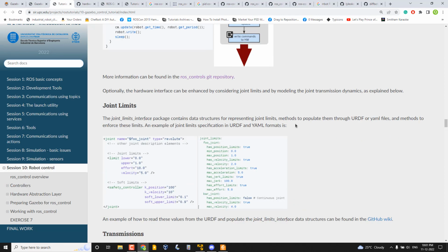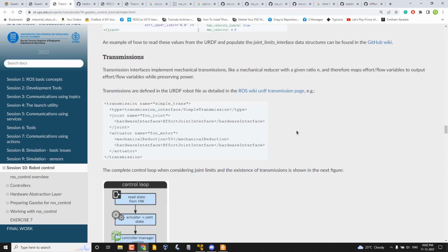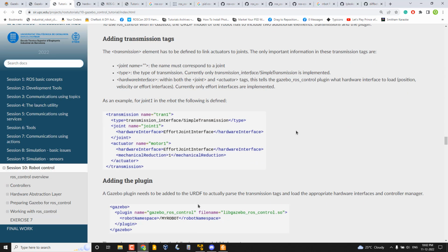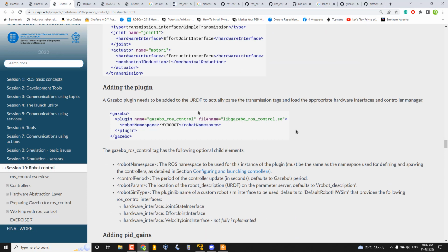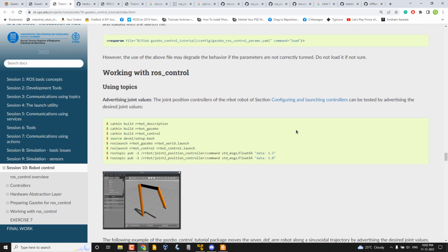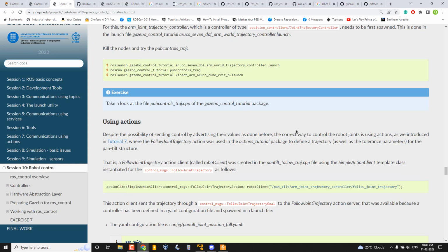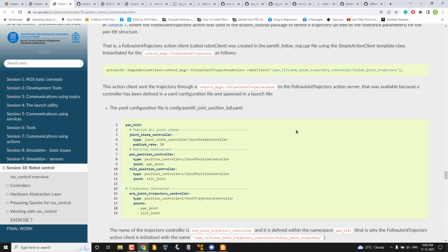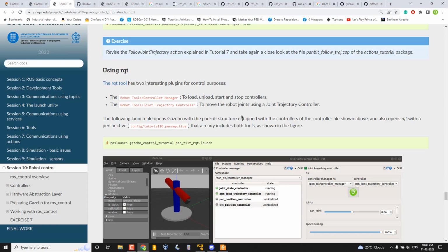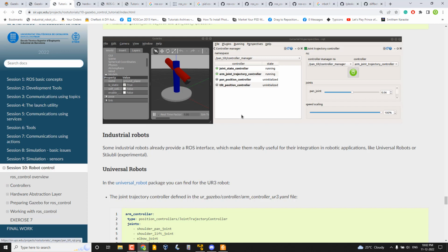Basically, we are writing a bridging code which can take commands from the controller to the actual hardware, then the feedback from the actual hardware to the controller. Just understand that, then you will get an idea. So that is the hardware interface code to connect the robot to the actual motors.